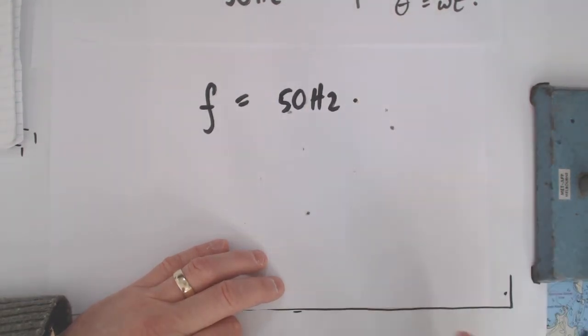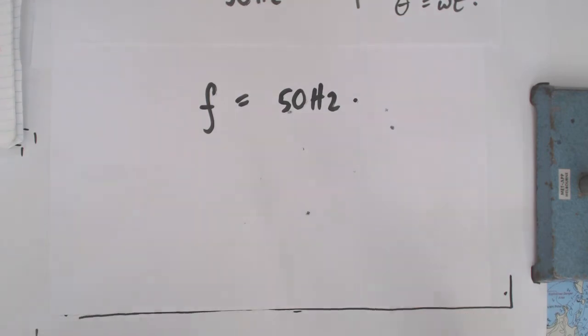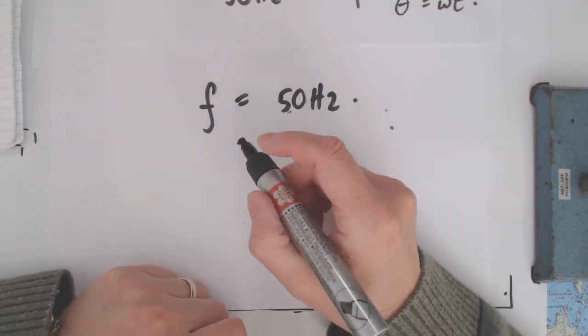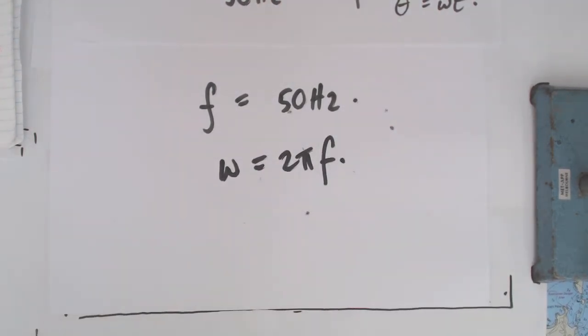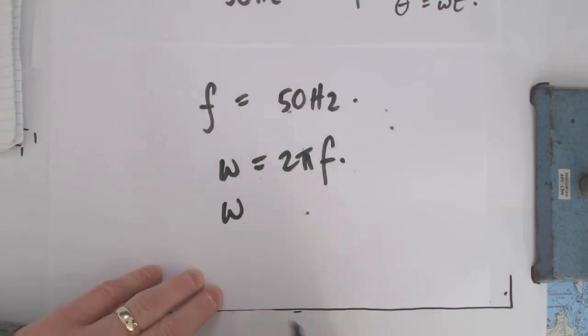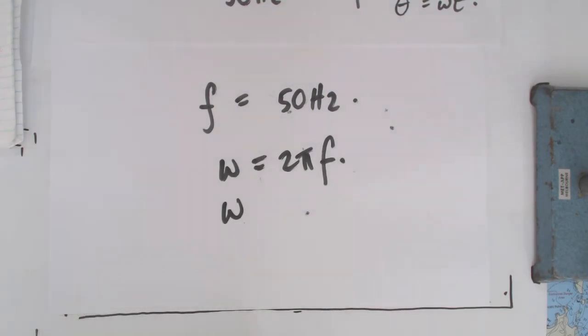That's a frequency. That's degrees, so that would be 360 degrees, all right, that it does every second. So how many radians is that? All right, well, that's 2 pi radians. All right, so 2 pi f, so omega equals 2 pi f. All right, that's radians per second. Divided by 2 pi will give you the frequency, right? Do we see that? So omega is radians per second. Divide that by 2 pi, and you've got the frequency.